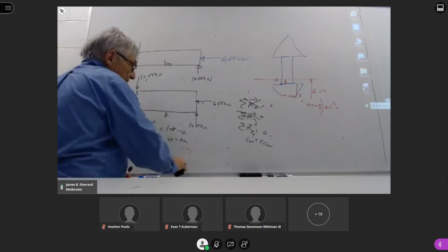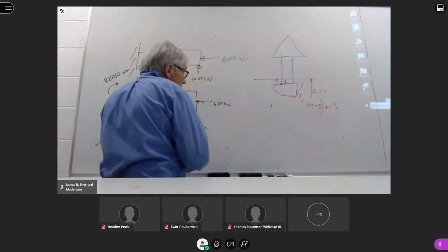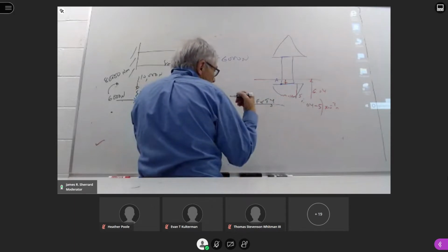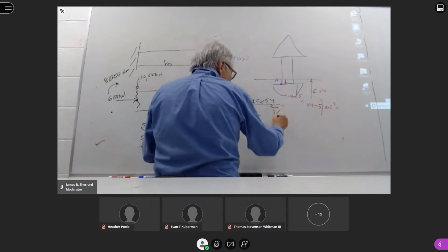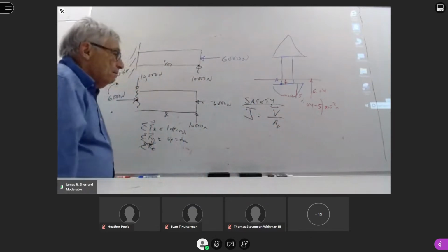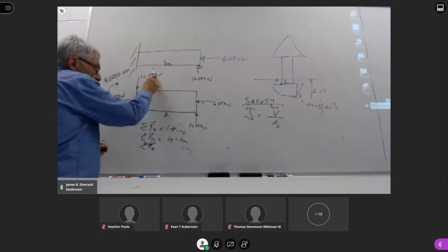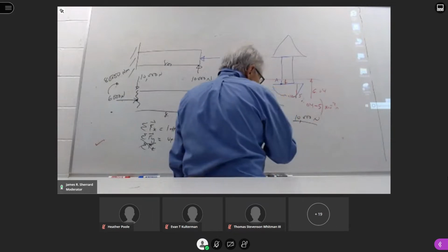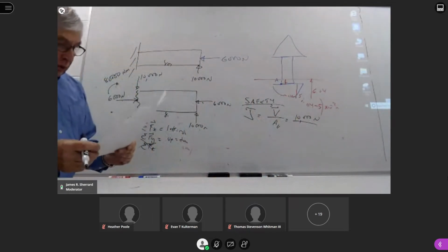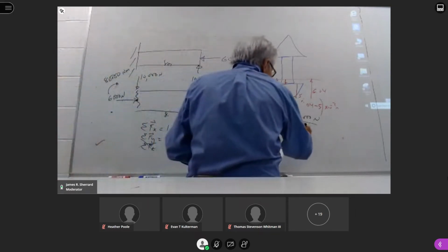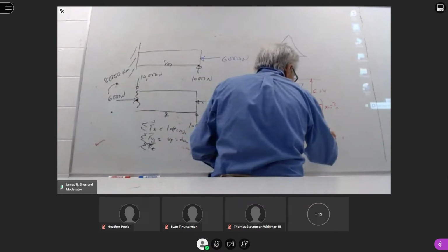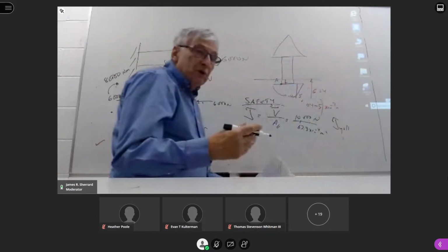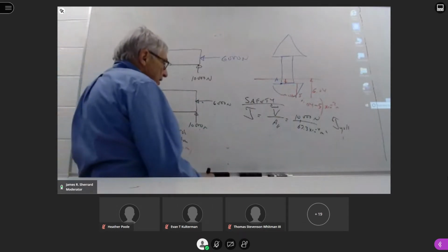If we then go back to look at safety, and again, if we look at shear stress, we know that's equal to shear force divided by the area parallel to it. And again, anywhere you cut this vertically, this is going to be my 10,000 newtons divided by that area, which was, excuse me, 67.3 times 10 to the minus 4 meters squared. And we compare that value to the yield value. If you do that, nothing has changed from before.